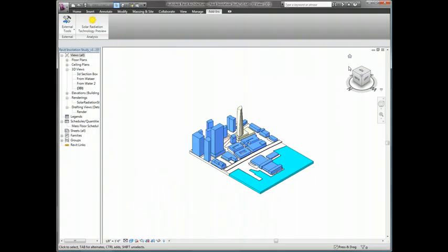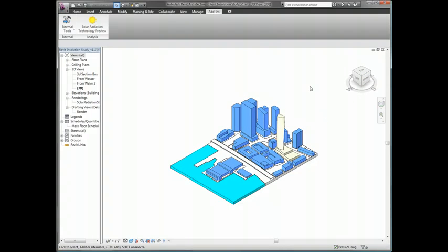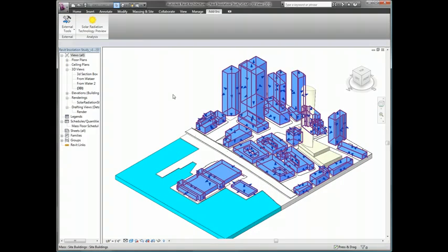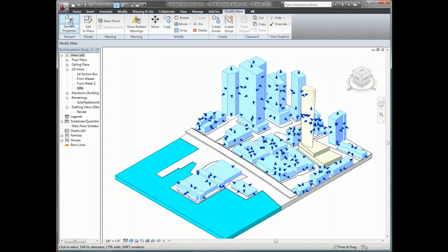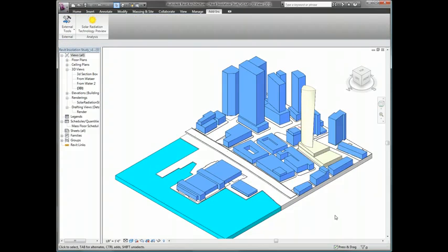What I need to do is mark many of the buildings on my site as shading only before I run the analysis. I can do this one surface at a time in the analysis dialog, but to speed up the process, I can pre-tag some of the buildings as shaded before I open the analysis dialog. By entering shade in the comments section of the context building mass properties, these buildings will only have a limited involvement in the calculations that I run. Any surface marked as shading will not have solar radiation calculated for them, but they will impact the calculations for other surfaces that are marked as analysis.